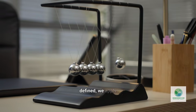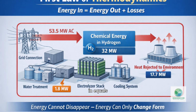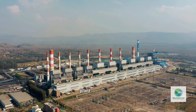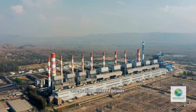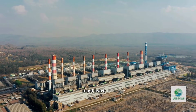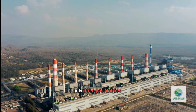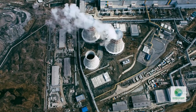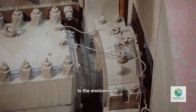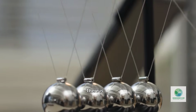Once the boundary is defined, we apply the first law of thermodynamics. Energy in equals energy out plus losses. In this case, the total electrical energy entering the plant boundary is 53.5 megawatts of alternating current power. That 53.5 megawatts must leave the boundary in another form. There are only 3 possibilities. It leaves as chemical energy stored in hydrogen, as thermal energy rejected to the environment, or as conversion losses within electrical and mechanical systems. There's no fourth category.